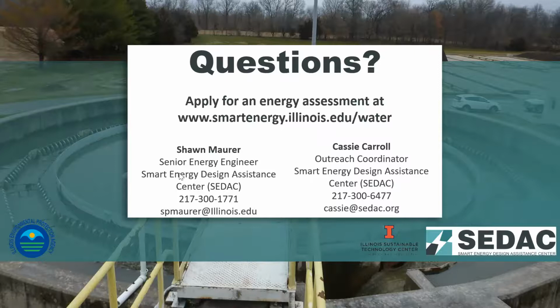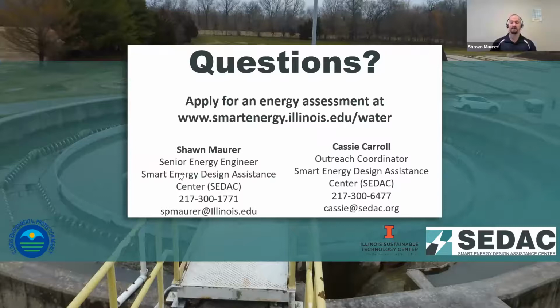on maintenance. We've also done some audits ourselves, and we've noticed that uninsulated pipe in a gas system, if you actually put 1 inch of insulation on an uninsulated pipe, you could reduce those BTUs by up to 90%. If there's any people that have any questions about that, I can always talk to the plant operators with that, or with CDAC itself. Yeah, that's a great point.